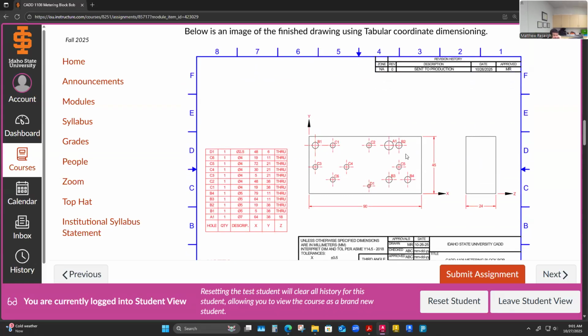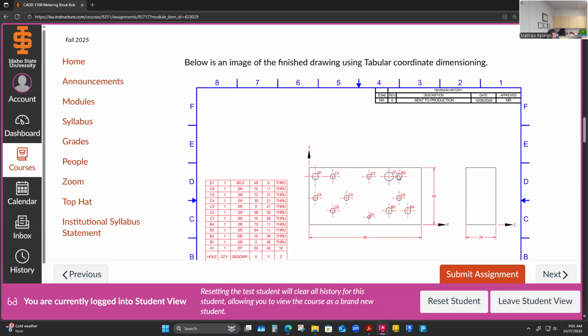It looks like I did a more systematic approach and put most of my view labels upper right. But this is just drafter choice. There's no code driving you on where you place your feature label. And like I said, you could point to it with a multi-leader too, and it might just get kind of busy. So I feel like just dropping the multi-line text is maybe the simplest way. And with that being said, I'll go into the weeds a little bit on view labels.